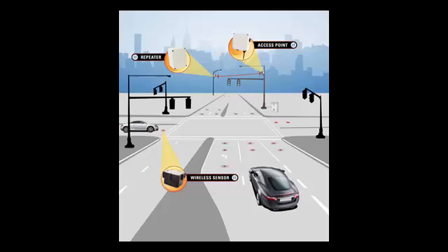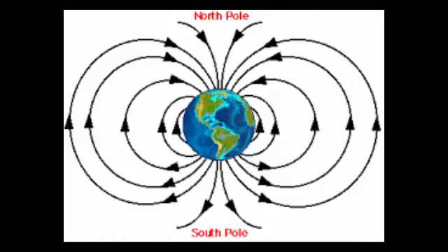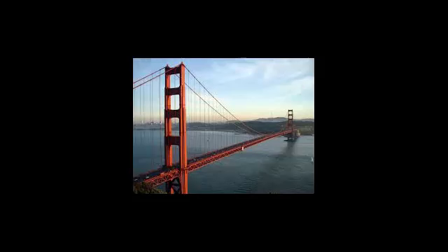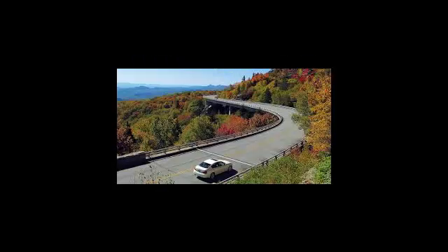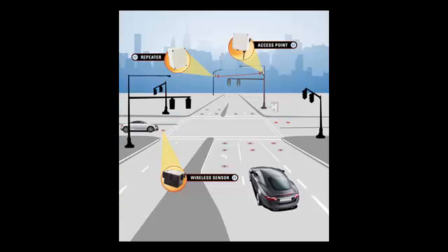Magnetometer measures changes in both the horizontal and vertical component of the Earth's magnetic field. Magnetometers are useful on bridges, decks, and viaducts where the steel support structure interferes with loop detectors, and loops can weaken the existing structure. The magnetometer consists of small in-road probes, a leading cable, and an amplifier.